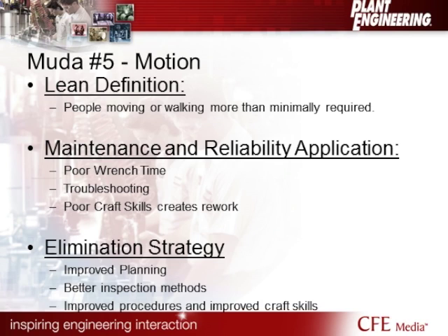Maybe someone's not familiar, and I worked in a facility years ago where there was a lot of really good people, and they really wanted to be successful at their job, but unfortunately, they really hadn't learned a lot of the newer techniques. They hadn't really been trained on anything new in quite some time. So a lot of the work that they were doing was actually introducing defects into the facility. One in particular that comes to mind for me, they had belts within that facility, and no one had ever taught them that you could take a belt or a sheave gauge and put it into the pulley and see if it was bad. So in reality, there were quite a few failed pulleys within that facility.